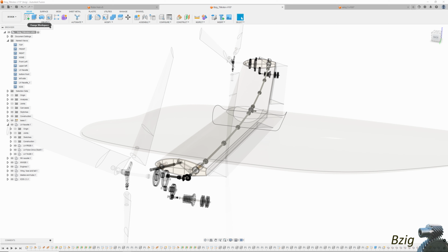Tilt rotors are fault tolerant of engine failures, but they are not fault tolerant of thrust asymmetry. This is different from multi-engine airplanes. Airplanes are capable of flying when one side of the aircraft loses thrust. This is because this thrust is designed to be as close as possible to the center line of the aircraft, and because the engines, when compared to a hover-capable tilt rotor, simply don't produce that much thrust.